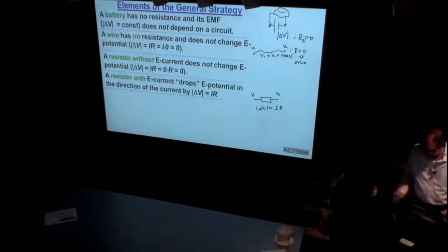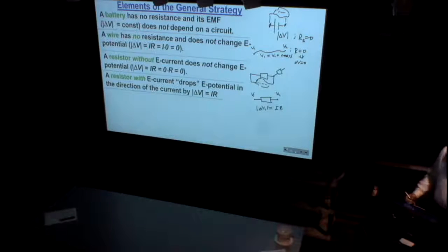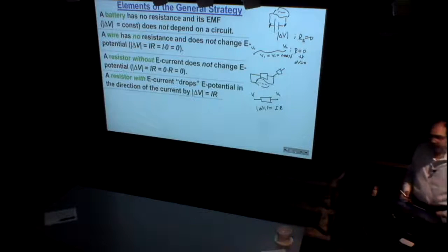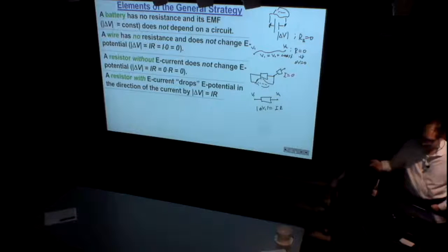But there might also be a situation when a circuit has some complicated part, wherever it is, doesn't matter. But also we have a single resistor seemingly connected. But is it? No. A connection means that both ends of a device should go to some part of a circuit. And here only one end is connected, the second is not, which means electric current has to be equal to 0, because the electrons cannot leave that end, it has to be connected.